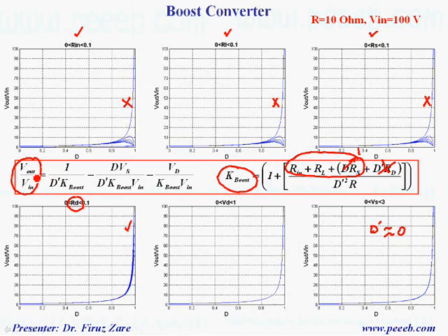So if we look at the conversion ratio, that's why at high duty cycle K boost will be different, and in this case we can see this will be the conversion ratio, and because K will be significant, this term will be pretty low at high duty cycle for different resistors.